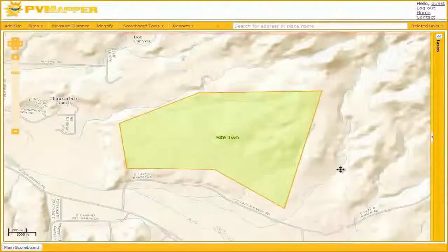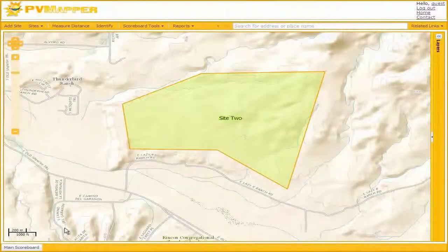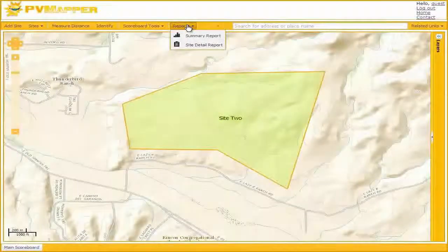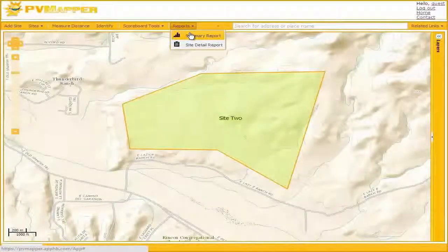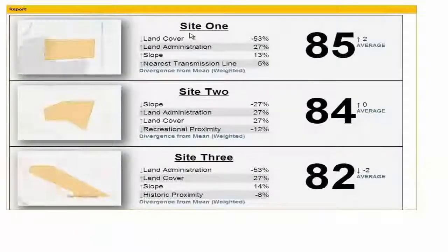And Site 2 seems to be built on a mountain slope. That's difficult to see just in satellite imagery, but we can turn on a topographic map and the slopes will pop right out. Looks like most of this is a south-facing slope, so this may be advantageous, but it may also be a problem. Site 2 may warrant a further study.